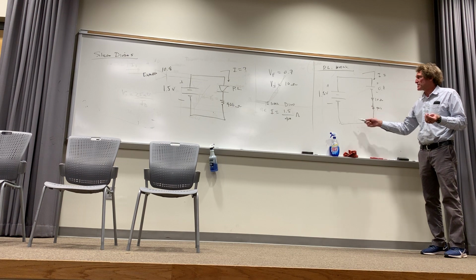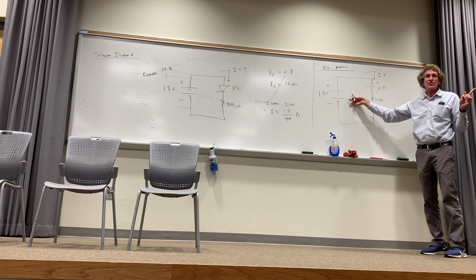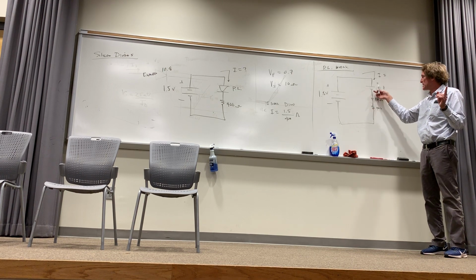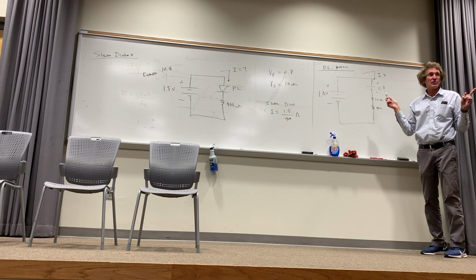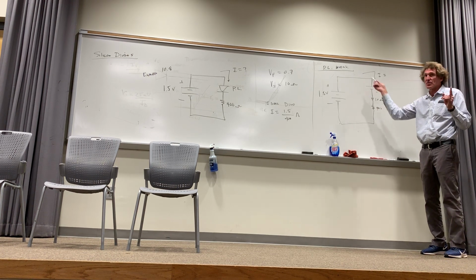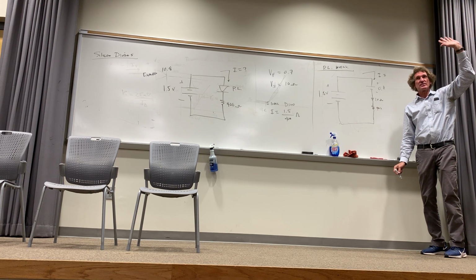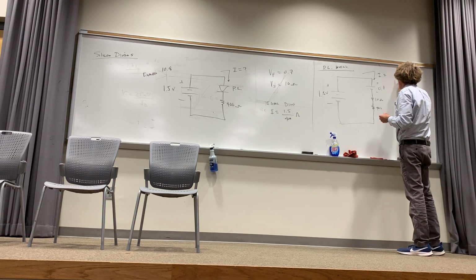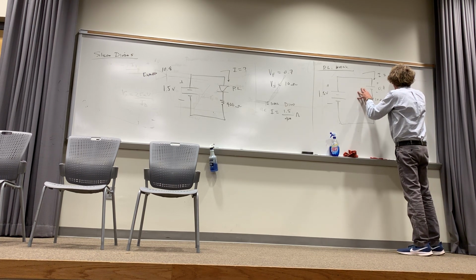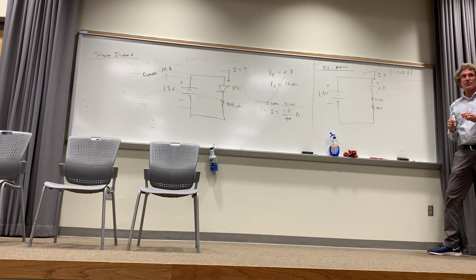All right, if you look at this, how much voltage is actually trying to force current around? I've got 1.5 trying to force it, right? But it has to overcome 0.7. So 1.5 minus 0.7 would be the actual voltage left to force current around. How many see that? Class, I'm talking to you as I would talk to my students in electrical engineering. This is the way I think about this. So when I look at the current that's flowing, it's going to be 1.5 minus 0.7. That's how much voltage there is after it overcomes the 0.7 of a volt threshold. With me?